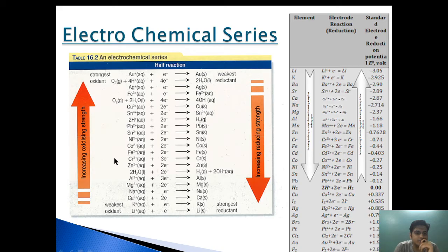As you can see here, the zinc, okay, here is the zinc and here is the iron. So zinc is acting as an anode and iron is acting as a cathode. So if we come here in this form, as you can see, zinc is having a potential of 0.76 compared to the iron having 0.44. Hence, zinc is more active compared to the iron.